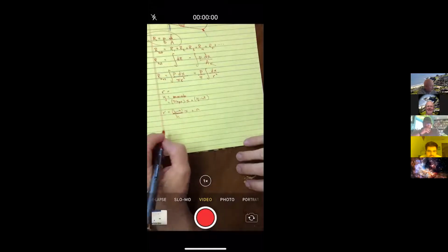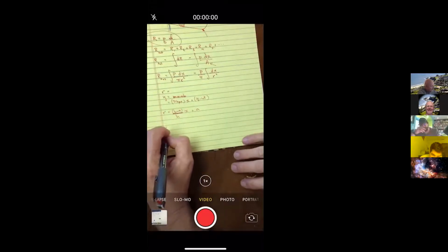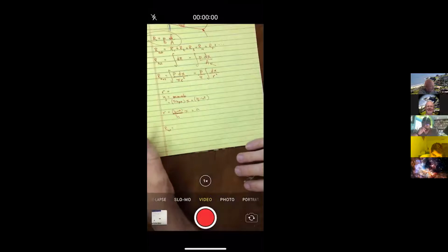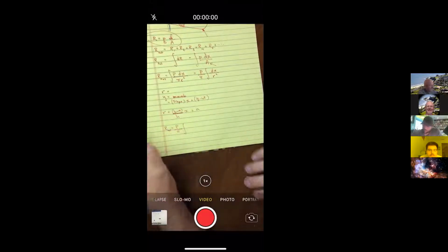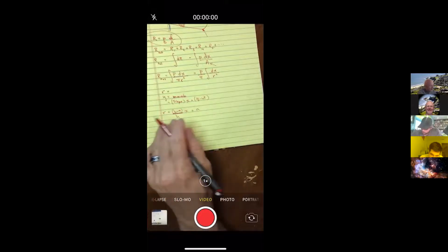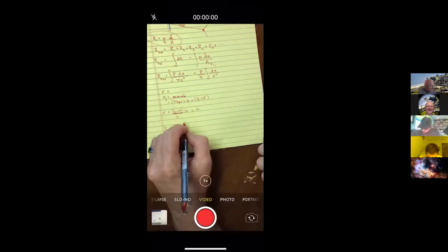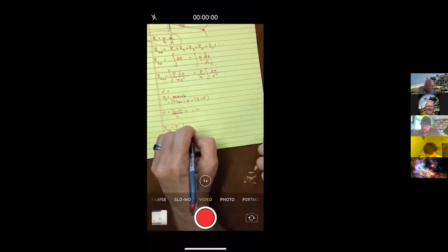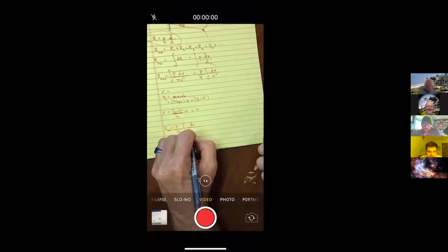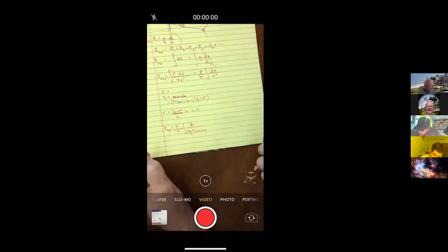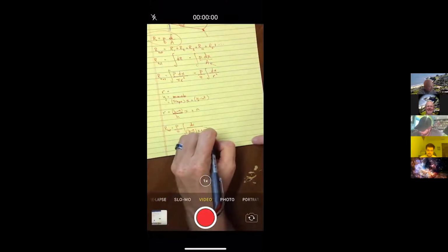So I can now use that and say, okay, R total equals, and I have the rho over the pi. And now I can write this as a, I'll leave the dx alone upstairs. But here's the big one. I get the b minus a over h times x plus a, quantity squared.